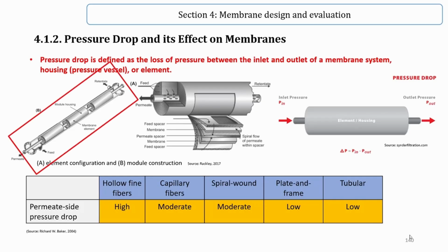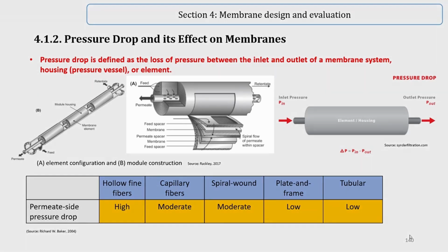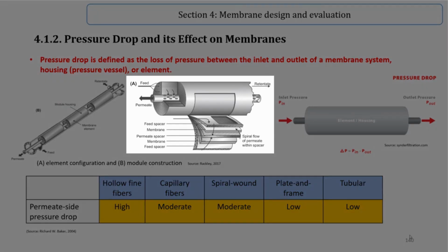Pressure vessel systems typically operate at transmembrane pressure, a pressure drop between the feed and permeate, between about 0.4 and 1 bar. Pressure vessels can be configured with either outside in or inside out membranes. In spiral-wound modules, designs minimize the pressure drop encountered by the permeate flow traveling towards the central pipe.